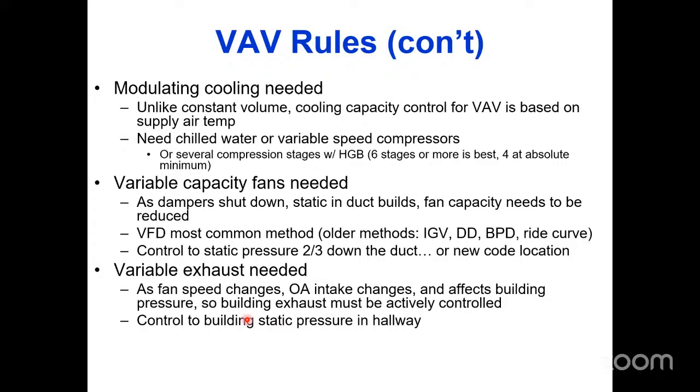And that sensor is going to be set up typically to maintain approximately 0.05 inches of static. So some job it might be 0.03, another one 0.08, but something in that general range, which is a fairly low amount, but that's the pressure from inside to outside. So I have a differential pressure sensor. One end of the pneumatic tubing goes outside, the other one goes into a hallway, and I maintain building pressure that way.